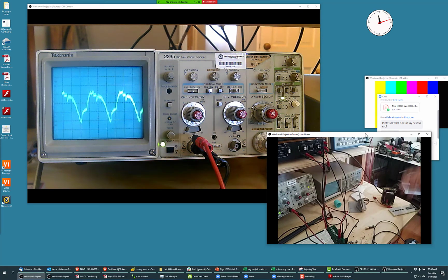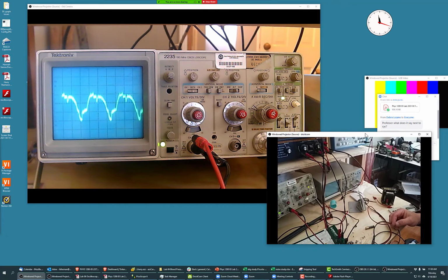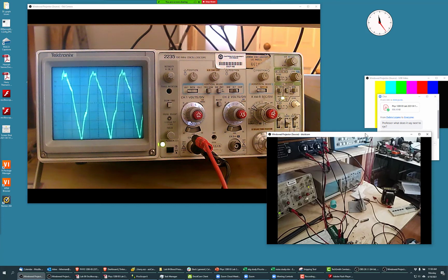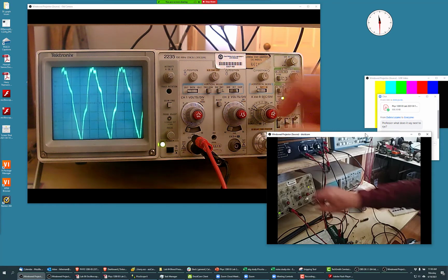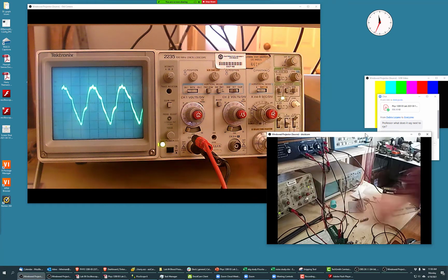And what is happening there is that, of course, it's triggering on the frequency of where the object is plugged in, which of course happens to be 60 hertz. Now I've connected it to an antenna I have out the window, and you can really see that the 60 hertz noise is the bane of our existence.